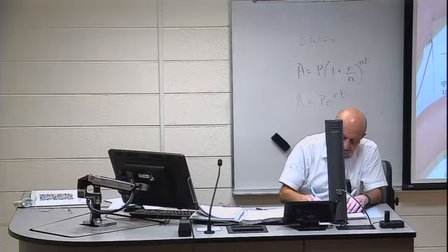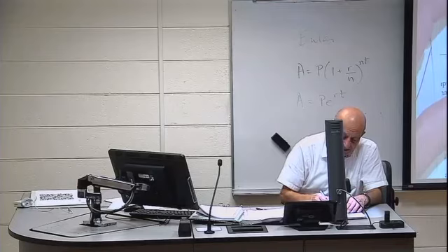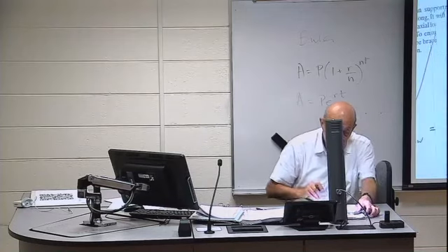And then I divide everything by EI. So then I get the second derivative of v with respect to x plus P divided by EI times v equals minus P e divided by EI.